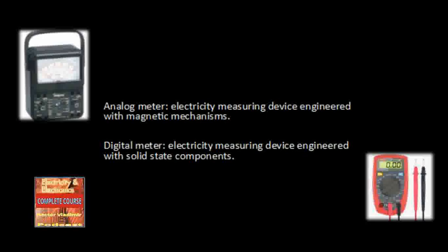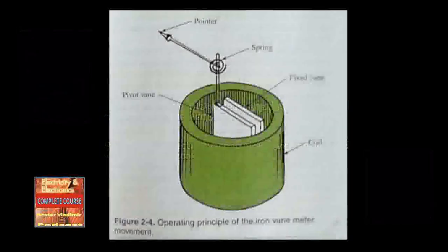The proper multiplier resistance may be used to increase the range of the meter. Multiplier resistance will be talked about shortly. A selector switch is used to select proper ranges. When used as an ammeter for current, the solenoid has a few turns of heavy wire. This is because the coil must be connected in series with the circuit and carry the circuit current.